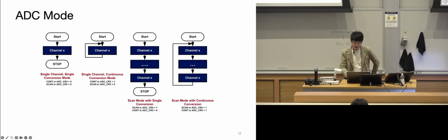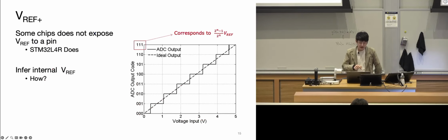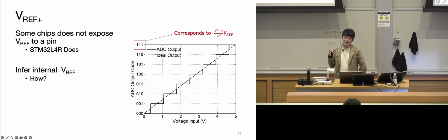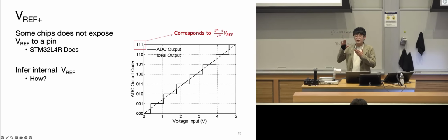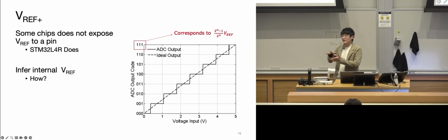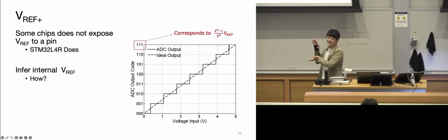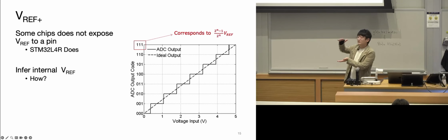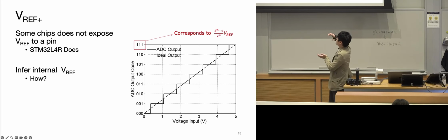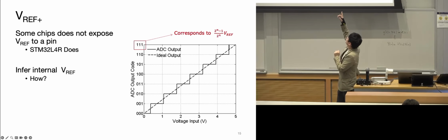Okay. Another thing to keep in mind is the V reference. In most of the examples you've seen so far, we try to change the signal gain before it reaches the ADC channel, right? We usually set the ADC channel's range to be just ground to VCC or VDD, depending on how you connect it. But it's also possible to set a different value as the reference.